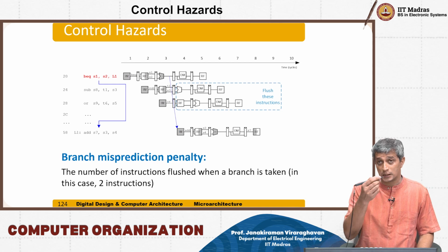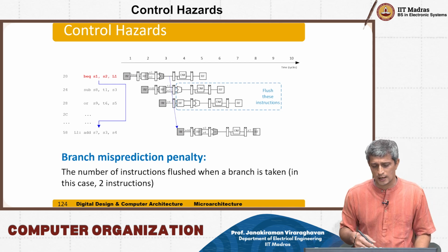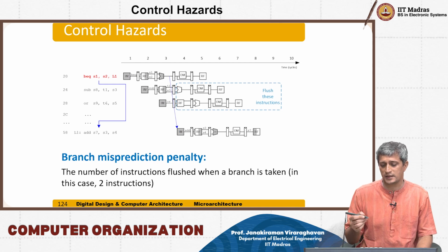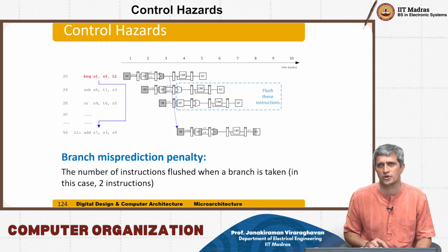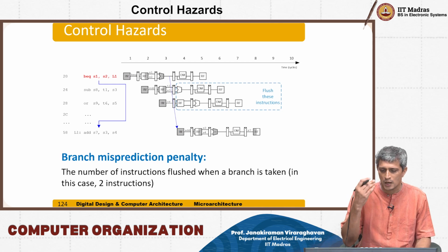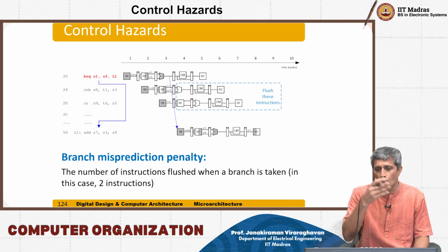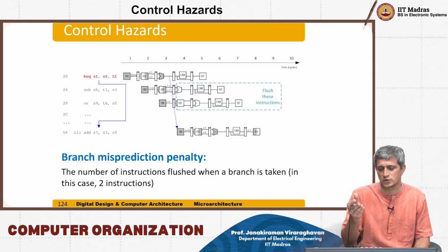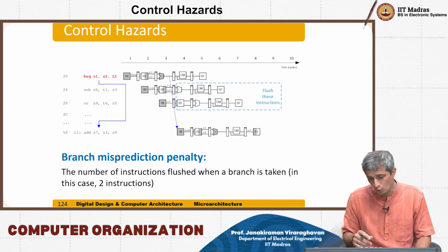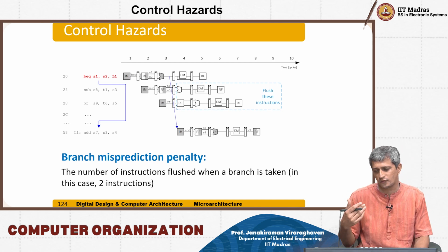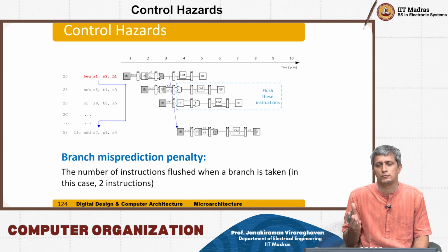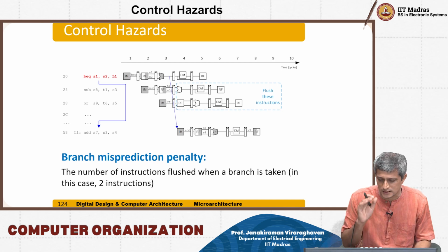But now, after the branch on equal, assume that the instructions are subtract S8 T1 S3 and OR S9 T6 S5. These are two R-type instructions. So while the register file is decoding the branch on equal register addresses S1 and S2, the subtract instruction is fetched, and then in clock cycle 3 the register file decodes the addresses T1 and S3.